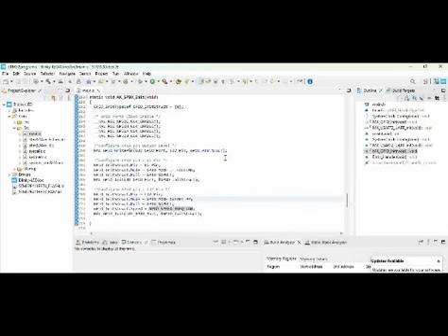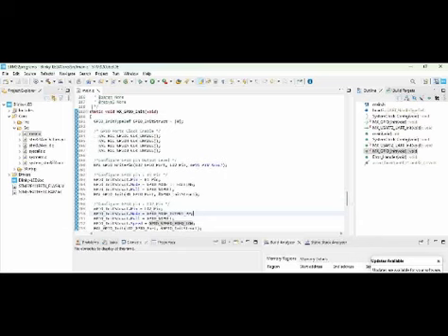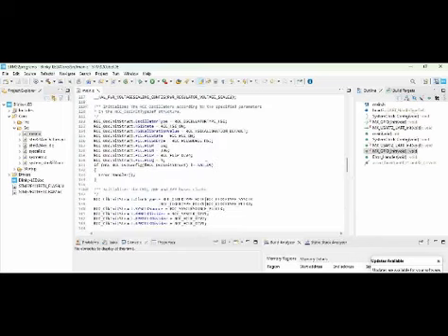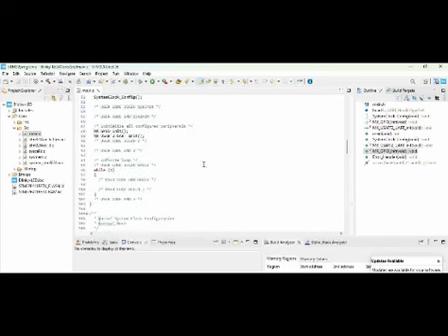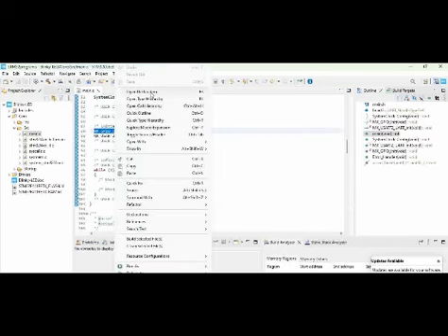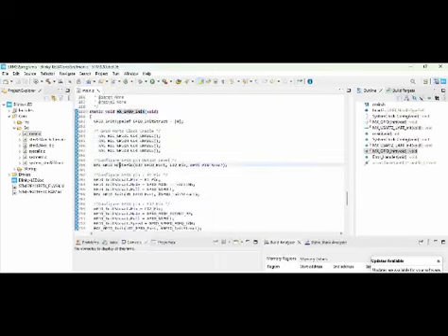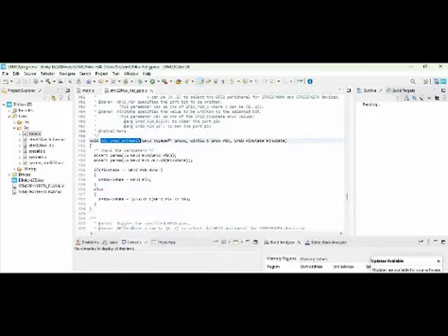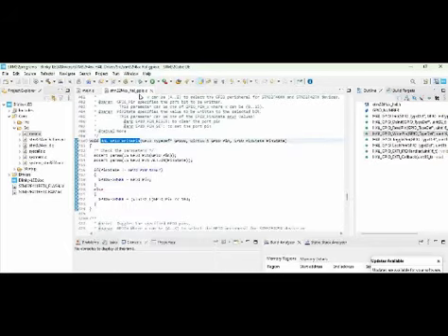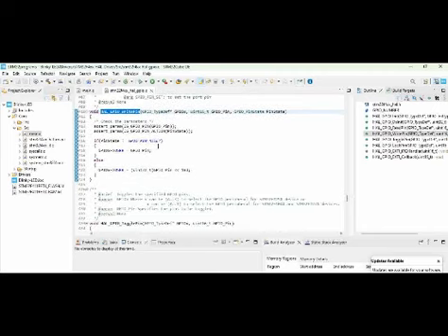Now we need to know how to toggle the pin, right? Go back to the while one, and to do that, first go to GPIO init and then to the GPIO write pin, where the function is. This is the GPIO.c, where the write function is defined. Below that, you will have something called HAL_GPIO_TogglePin. So this is the function which actually toggles.